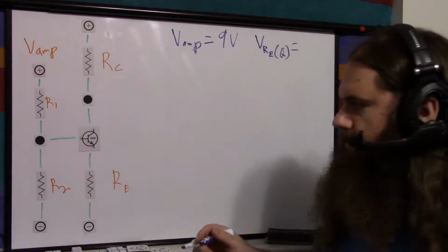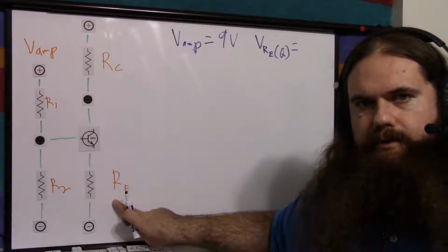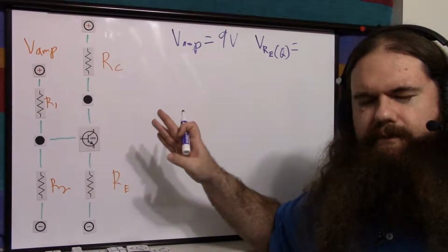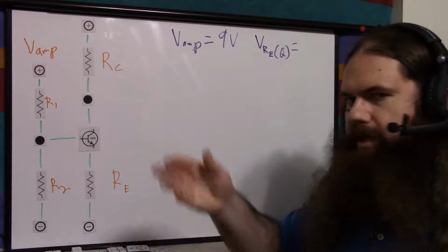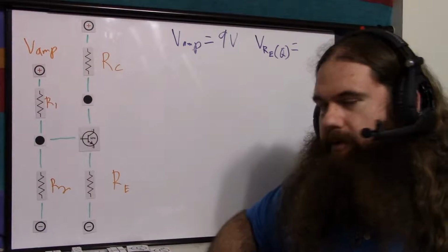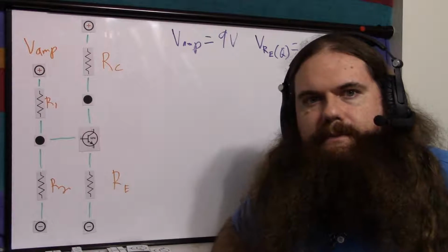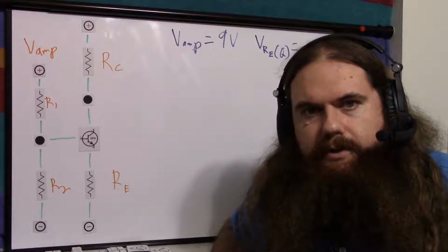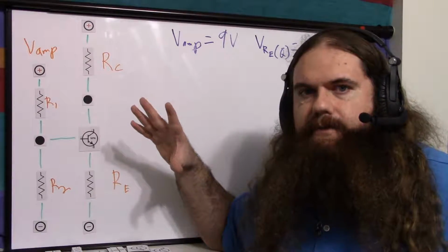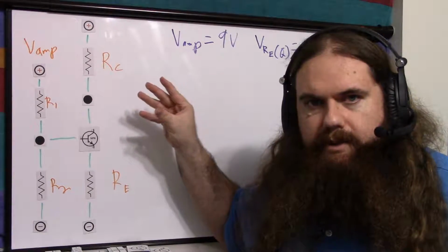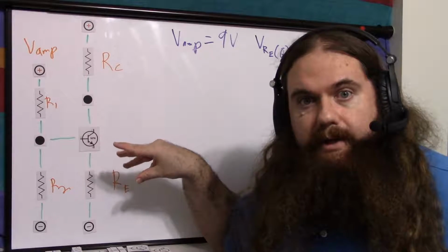And we've gone over this before. It should be 1 volt or 10% of the supply voltage, whichever is greater, is the rule of thumb usually. So 10% of 9 volts is 0.9 volts, so we just say 1 volt. If you had something like 24 volts, you'd probably want 2.5 volts or something. This is just a rule of thumb. Bigger is safer, but it's more wasteful and you lose gain. But you can make it bigger, just don't make it too small.